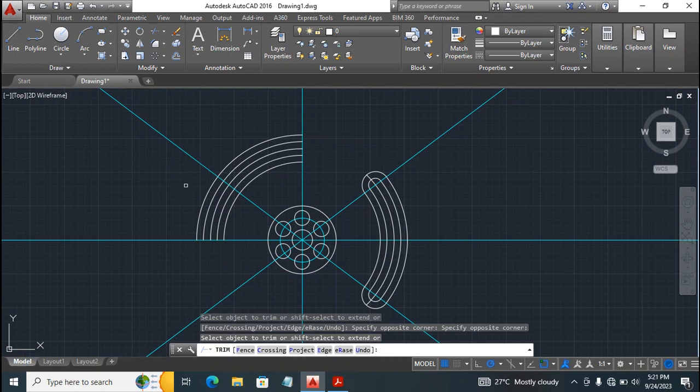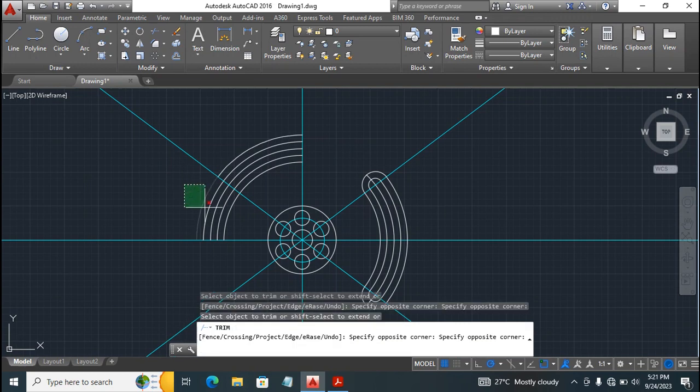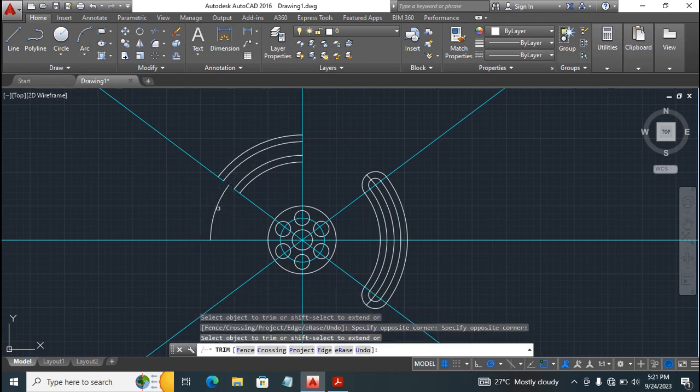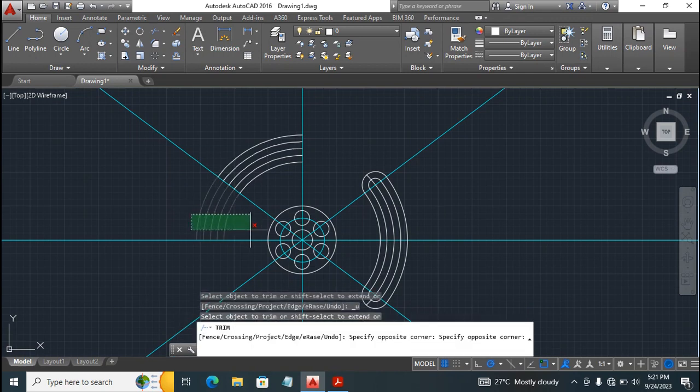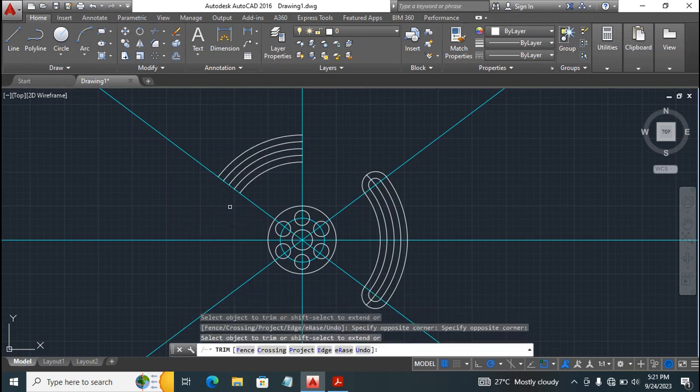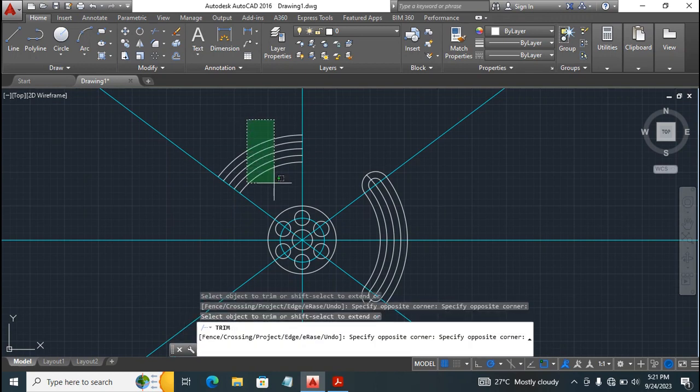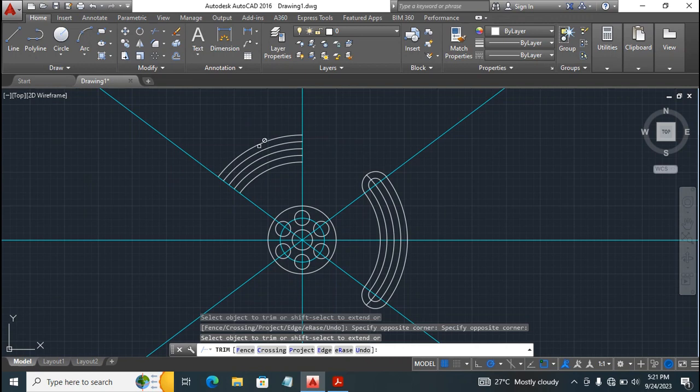Okay, so you see that's new. You can highlight all the lines you need to trim out at once. Just highlight them, left click on the mouse. That didn't go well. Ctrl Z. Highlight these ones. Alright, highlight this as well. Oh, that didn't go well because there is no intersection right there. So I'll just select it normally.